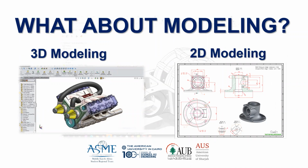And we have another type of technical engineering drawings, which is assembly drawings. So they're a little bit different than each other. I'm talking about working and assembly drawings, okay? Each of them has some, let's say, characteristics and some contents. Like an assembly drawing, we may have something like a BOM, bill of material table, or we take a cross section from the mid plane of the assembly to show how the components are positioned together and each other, the positioning of each component, okay?